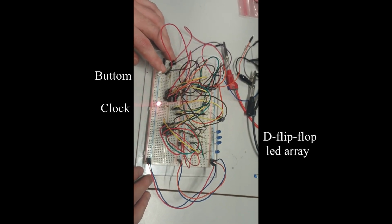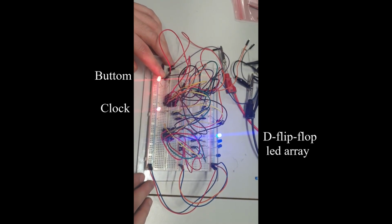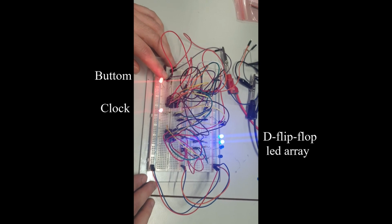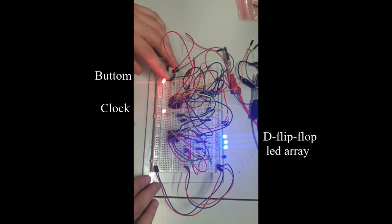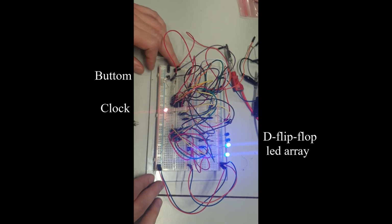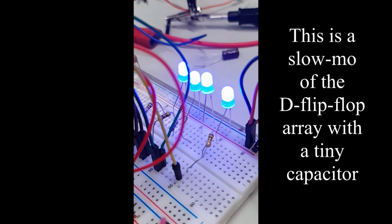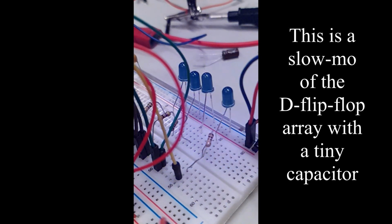Pushing the button down for at least one clock pulse sent an input value of 1 to the first D flip-flop, which then carried it on to the other flip-flops in line. The input value changed to 0 as soon as the push button was released. The input values traveled as expected with small capacitors, for example with the capacitance of 4.7 microfarads.